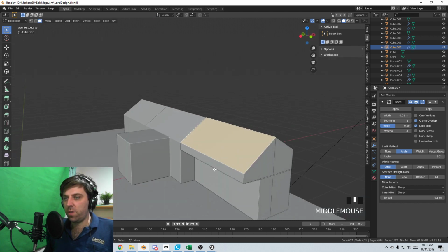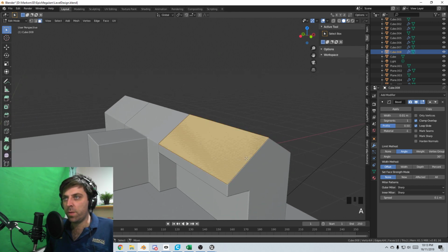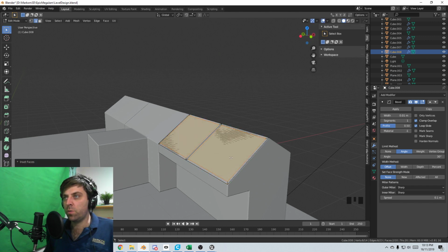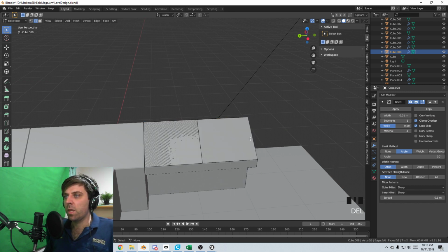So from here, let's go Shift D, P, separate by selection, and so this will be our console panel. Select this, put an edge loop through the middle, select all, I to do an inset, I again to do another inset. So we've got like two separate screens in there, and they can both have different data. Interaction wise, I am starting to lose my voice. So let's delete vertices and let's work with the one screen.